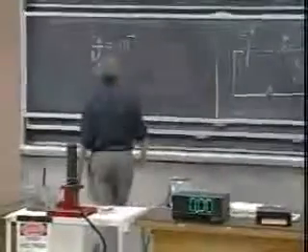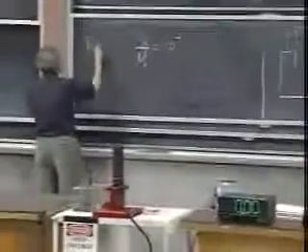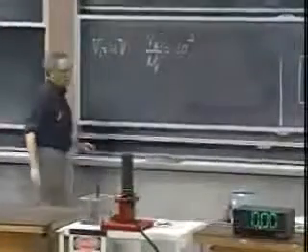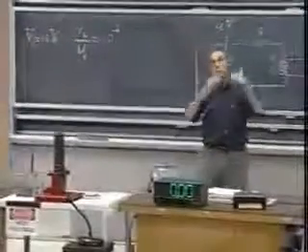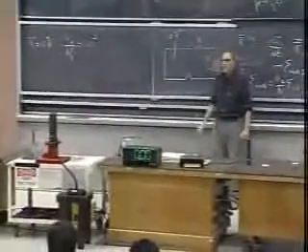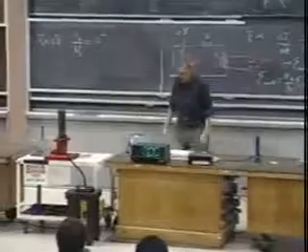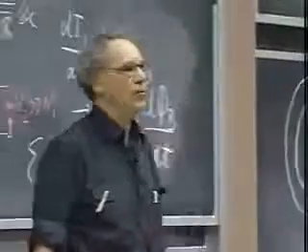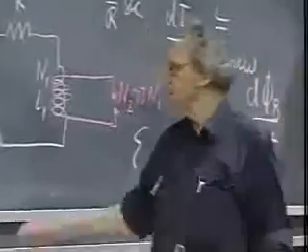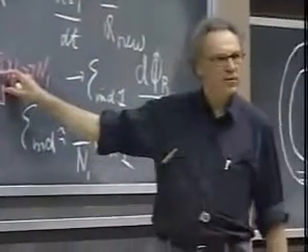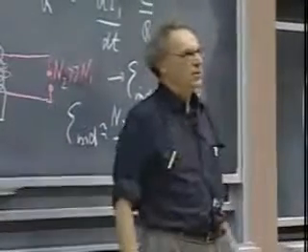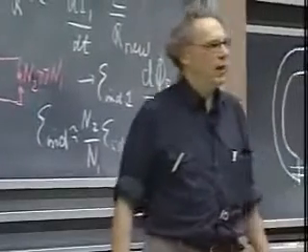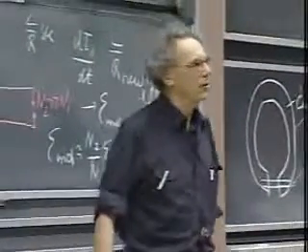And we run it with a car battery, just like your car, 12 volts. We let the current build up in the primary, just like we have here, and then in a very cruel way we open the primary, and we create in the secondary up to 300,000, 400,000, 500,000 volts. And then you will see a spark fly over here at 300, 400,000, 500,000 volts. You can draw a spark over a distance of 10 centimeters easily, because all you have to do is get above 3 million volts per meter, which is the breakdown electric field.